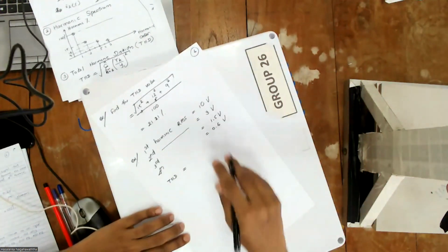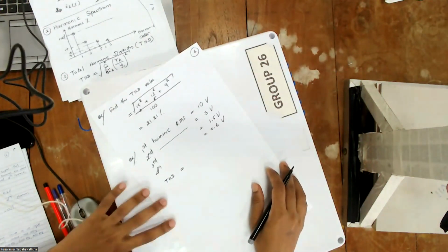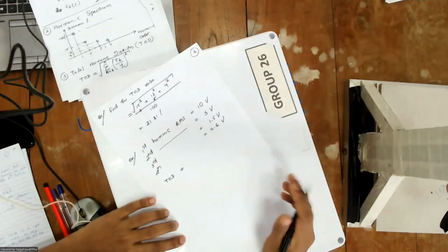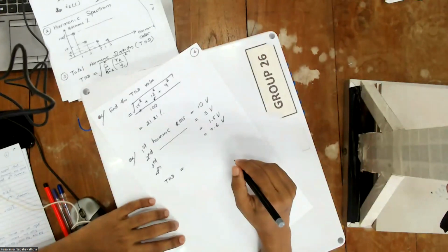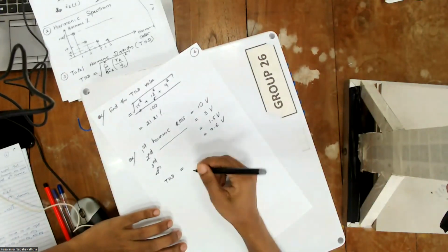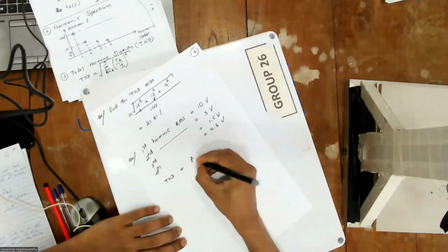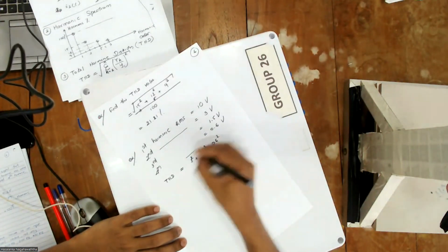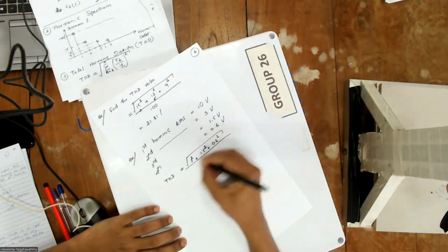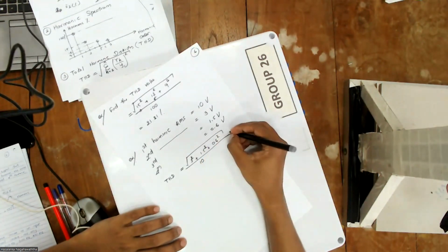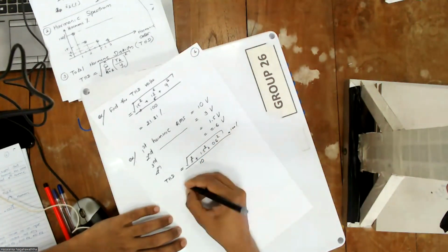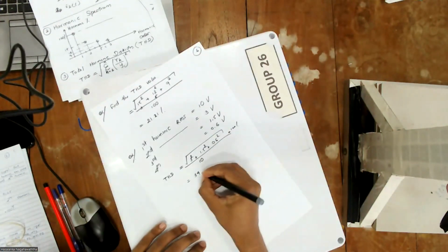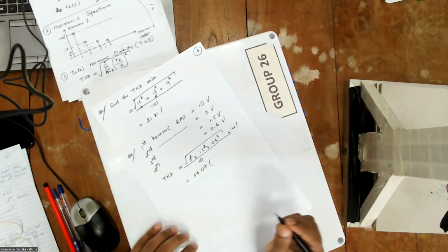If I give you amplitude value, you should be able to convert it, and show this step in the exam. So 3 squared, 1.5 squared, and 0.6 squared, square root, divide by 10 and multiply by 100. Then you should be able to get 34.07.